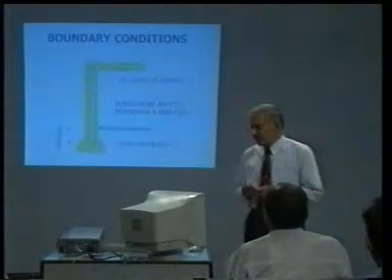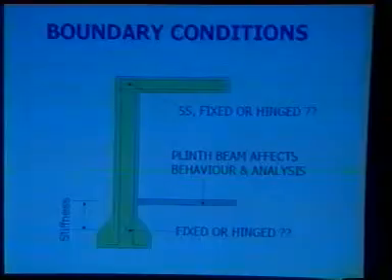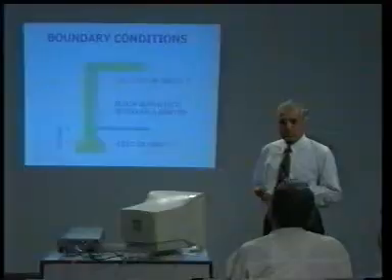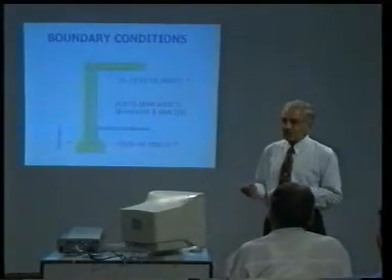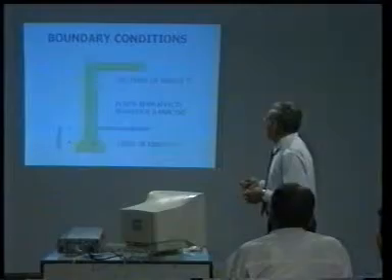Now, coming to the problem of boundary conditions. Now, at this place, if this bar and this bar are just left like this, or if this bar is taken inside and this bar is taken inside, it makes all the difference, whether it is a fixed condition or a simply supported condition. In RCC structures, gentlemen, a truly simply supported condition cannot be arrived at. So, you have a question of partial fixity.